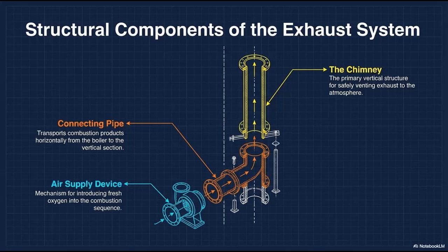We don't generally think of fire as having a diet, so to speak. Right, a diet. But sustaining a safe chemical reaction requires a staggering volume of oxygen. The numbers on this actually blew my mind. The source states that for every 1 kilowatt of nominal thermal power, a gas appliance requires 4 cubic meters of supply air. That is a lot of air.